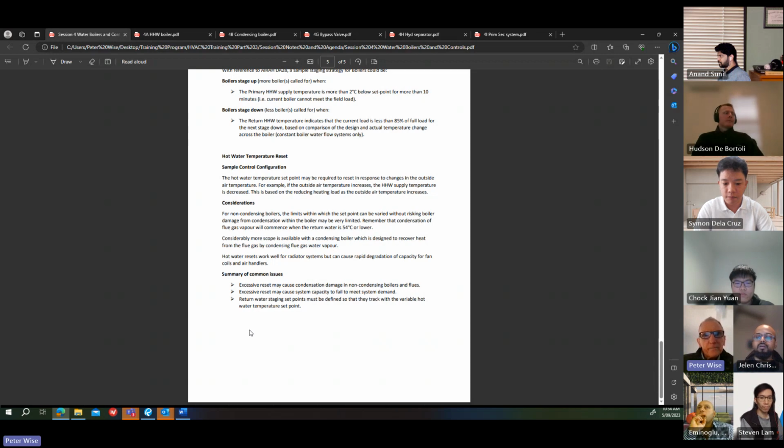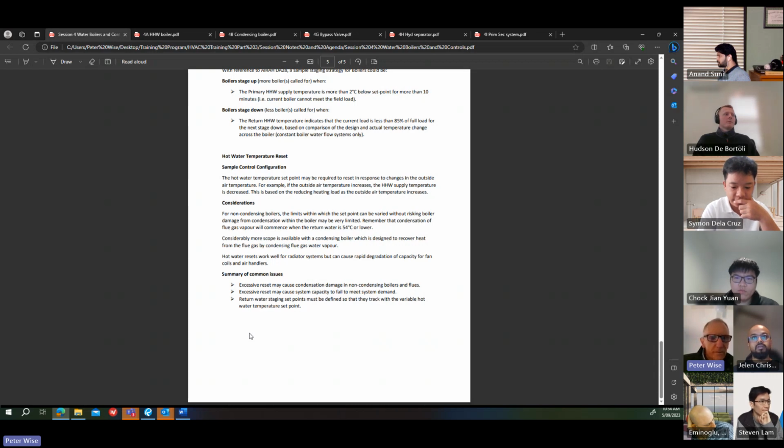So let's say the pump delivers 10 litres a second at 200 kPa, which normally goes out to the field. When the field is fully open, all that water is going out to the field, and it's all stable. Everything's fine. When the valves start to close, and the bypass starts to open, it's got to have a fairly high pressure drop so that it's not robbing water from the field initially.